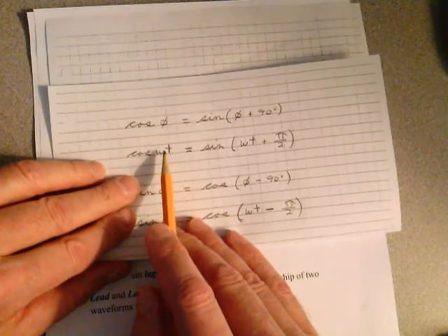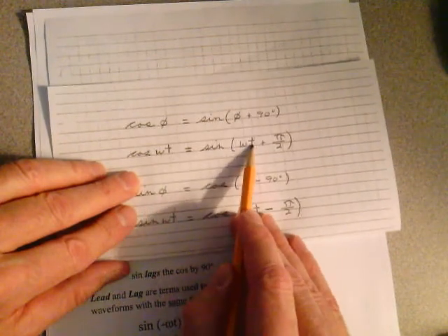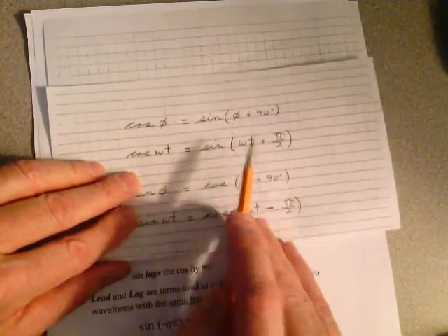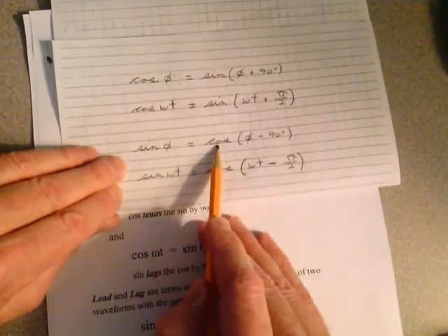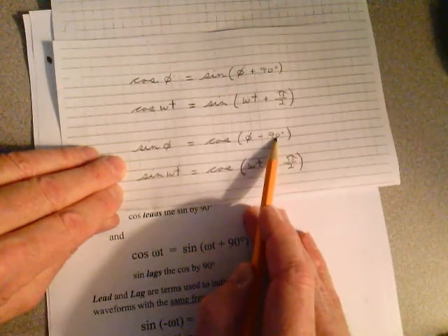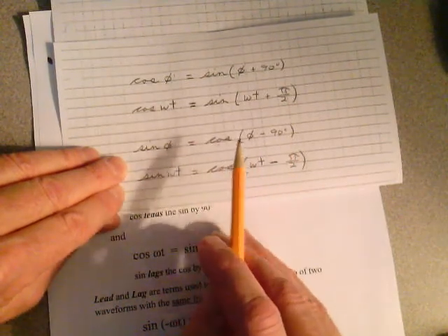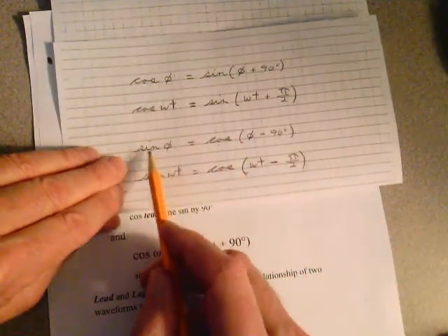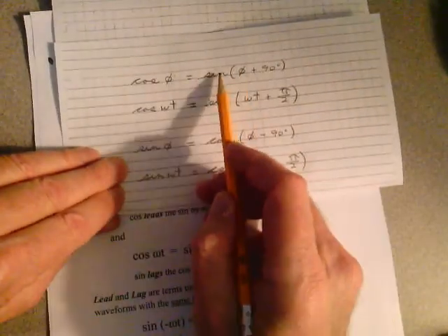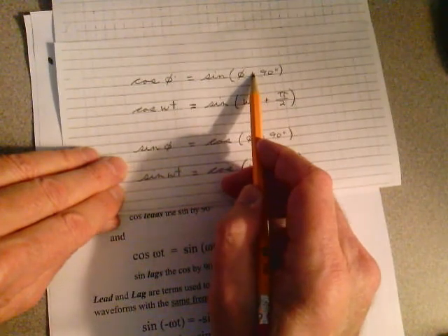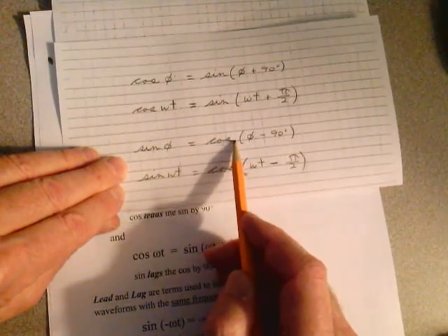In terms of the radian frequency, the cosine of omega t is equal to the sine of omega t plus pi over 2. Pi over 2 is 90 degrees. These are really the same equations. What about sine? Sine is equal to the cosine of the angle minus 90 degrees. Why? Because you have to slow the cosine waveform down. You have to move it back to the right, so it'll be a cosine wave. You either memorize these, or you think of it in terms of, what do you do to the sine if you want to get the cosine? You better add 90 degrees. What do you do to the cosine if you want to get the sine? You have to subtract 90, because the cosine is ahead of the sine wave.